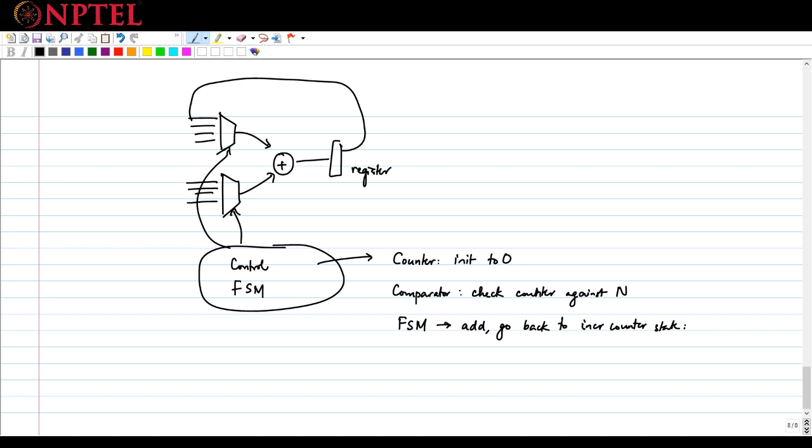Okay. In fact, I might even be able to do this with a single state, which means that in each state I will add 2 values, increment a counter, check whether the counter has exceeded its limit, and if necessary get out of the loop or continue in the same loop at the next set of values. Okay. So in terms of implementing for loops, this is one way by which you can do it. Okay. Hopefully that part is clear. We can also have further discussions, and I'll try to give more examples on the mailing list if this is not quite clear. Please let me know.